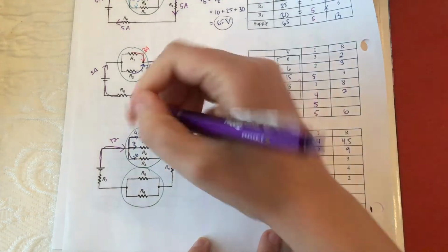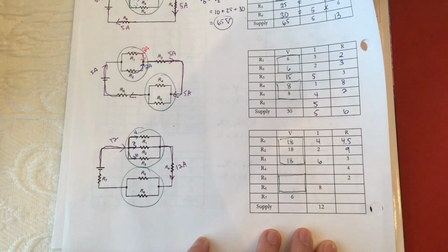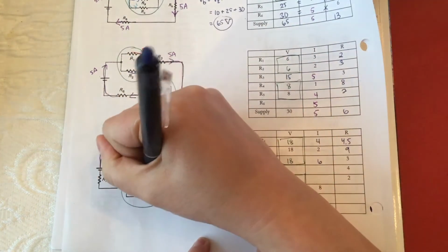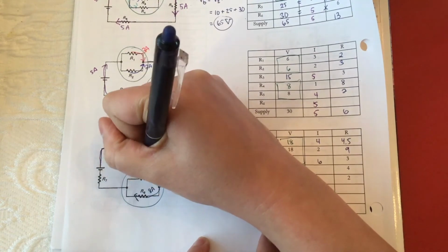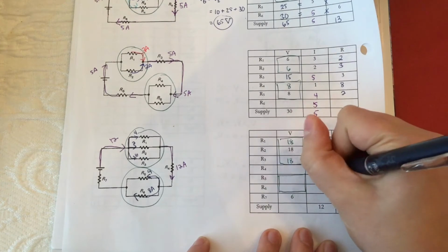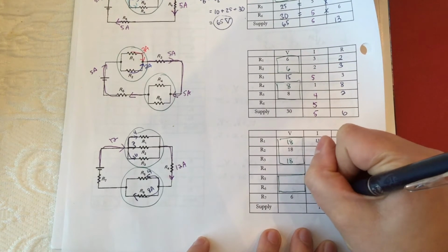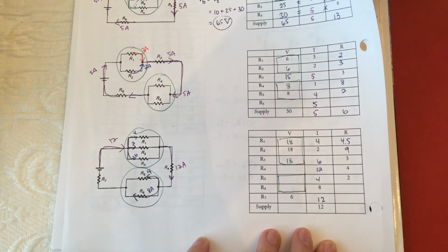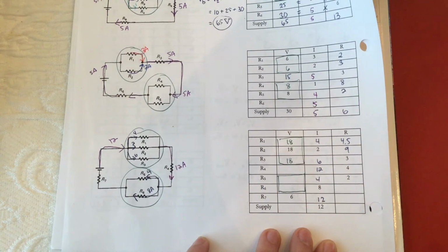That same 12 amps flows through R4 because it's only one path. It splits up at the junction so that 8 of it goes through R6. So that 4 amps must go through R5 to make your 12 total. If you picture this as gallons of water, that's a helpful analogy. This system has 12 gallons of water that might split up and go through different pipes at any given time, but it still needs to be 12 gallons.